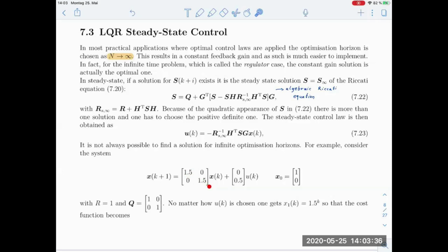Why do we see that here? We have a diagonal form in the system matrix. So the state x1 is not influenced by state x2 and the other way around. So they live in their own modes. It happens to be the same eigenvalue. It could also be different eigenvalues, that would not change our example now, really. Both of them are unstable, which is not a showstopper for control design, as long as we can access that mode properly.